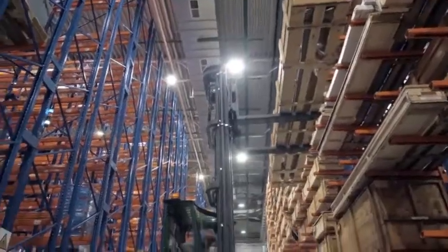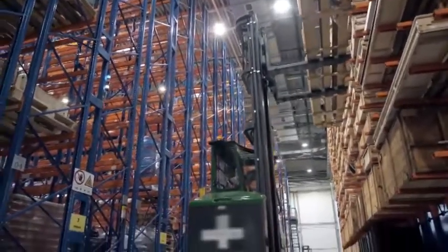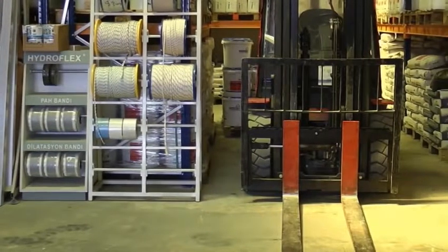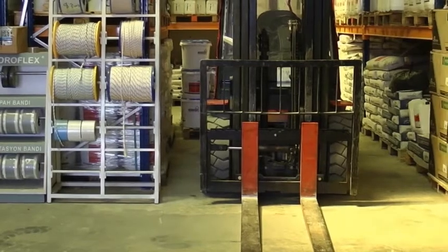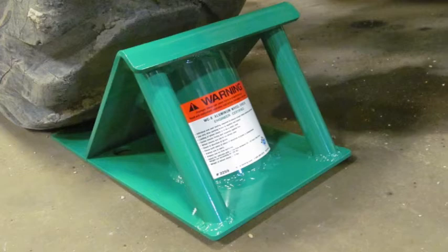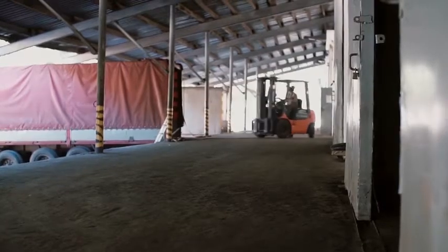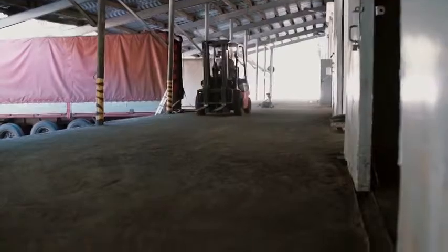Never allow a person to stand under or pass under the elevated portion of any truck, whether loaded or empty. When a forklift is left unattended, lower any load and neutralize controls, shut off power, and set brakes. Wheels must be blocked if the truck is parked on an incline. Keep a safe distance from the edge of ramps or platforms while on any elevated dock, platform, or freight car.